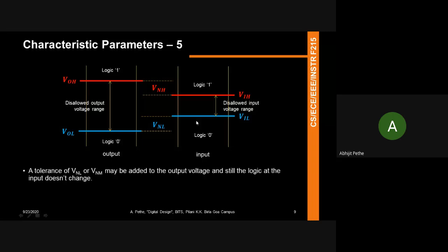So Parth, what it means is no matter where the V input is between 2 and 0.8 volts, it won't give an output of 2 volts. It gives an output between 2 and 5 volts, and that output depends on what else is connected outside. At the output node, if you have some other circuitry connected to it, that will dictate the node voltage at the output. If that output is just connected to a simple resistor, then it will depend on the resistor value. So 2 volts is the minimum voltage that is available for high, but it can be in the range between 2 and 5.